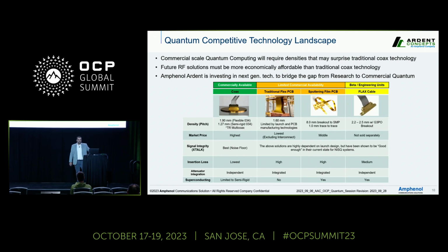At the core of the ganged coaxial solution showcased today lies a dual-sided compression interface. This interface design is capable of delivering the necessary levels of electrical and mechanical performance without the need for coax cables alone. Consequently, a variety of different transmission lines can be integrated with this interface, enabling greater densities than coaxial cables can achieve and potentially offering more cost-effective solutions.